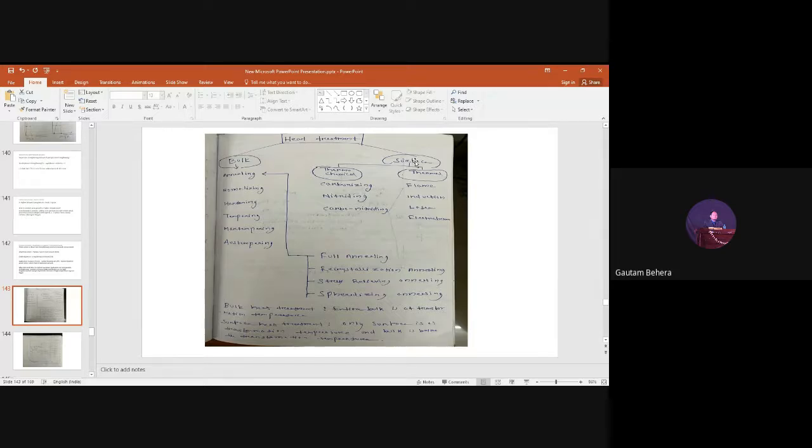The bulk will not be in the transformation temperature range. Or you can say the core part will not be in the transformation temperature, only the surface part will be, right? So we can heat the surface, like 1 mm or 2 mm of the surface, to the transformation temperature, but the bulk will not get heated up there, right?